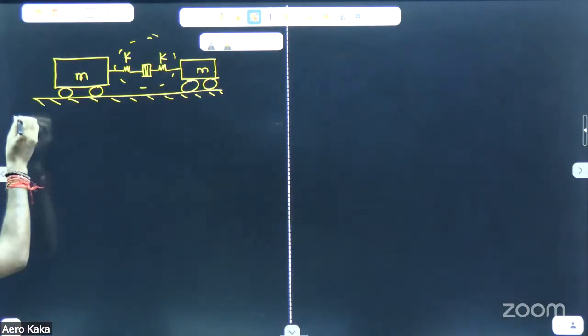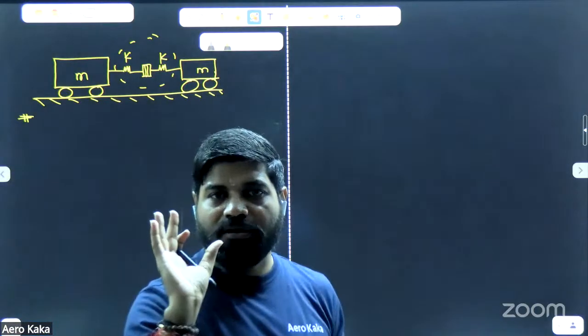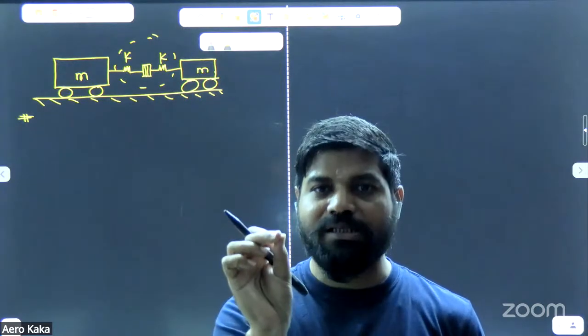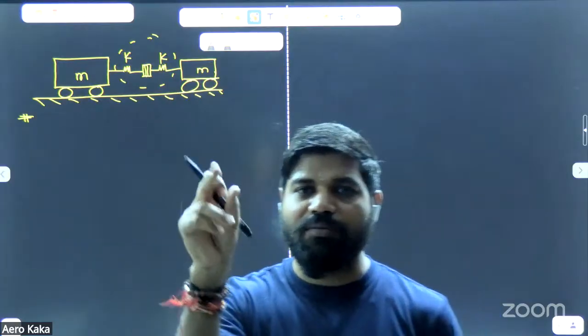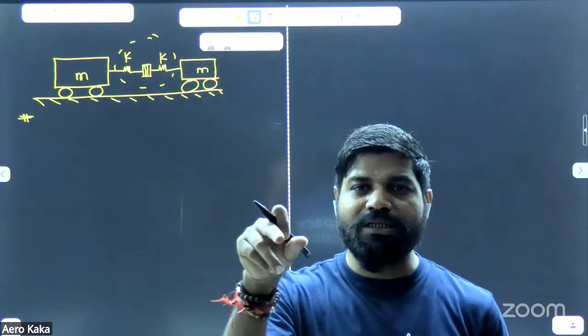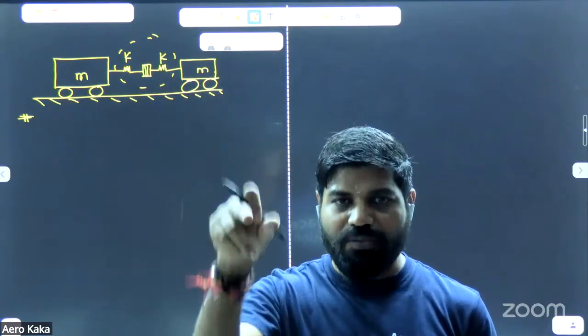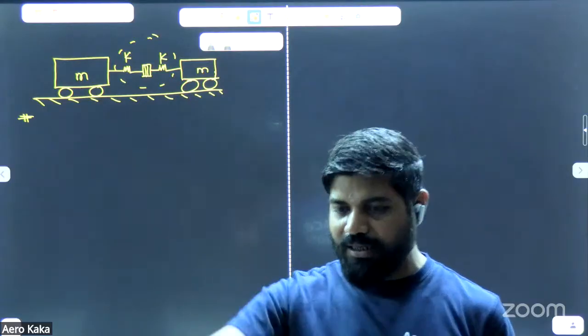Now, I can write here the frequency equation. So, just understand what is the frequency equation. That's m1 m2 omega raised to power 4 minus, in a square bracket, what do you have to write? (K1 plus K2) m2 plus (K2 plus K3) m1, square bracket close, omega square, plus, in a square bracket you can write, K1 K2 plus K2 K3 plus K3 K1. That's it.